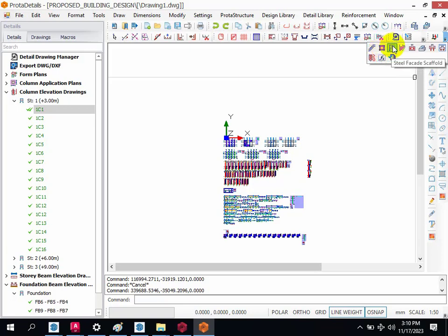So they are just templates. It's just like a common form filling. Once you finish filling it, click on generate to generate the drawing for you. It's as simple as this is cover, this is pad footing. In a case where you just want to design a particular pad, if you know the load, you can just do this part here to design the pad so that you will know the size of the footing that can be used.